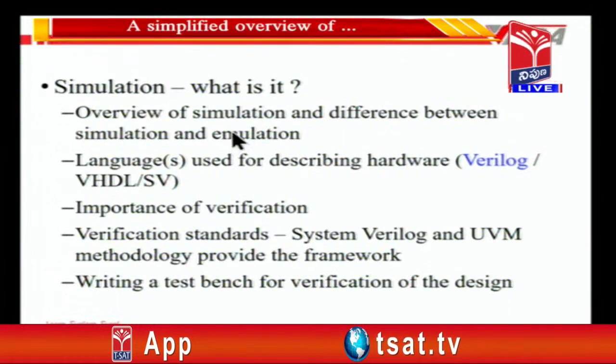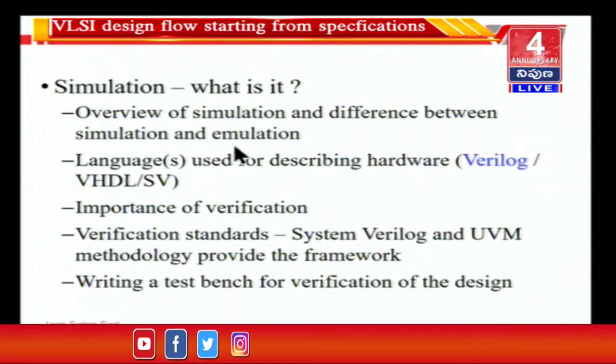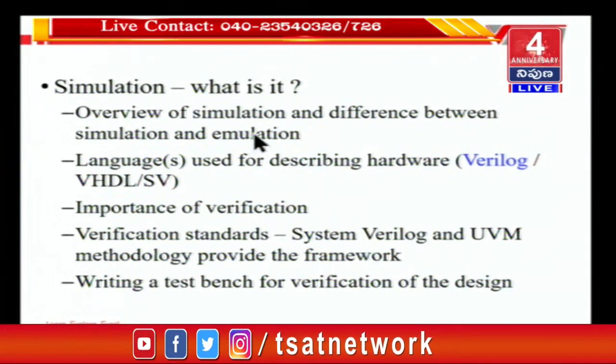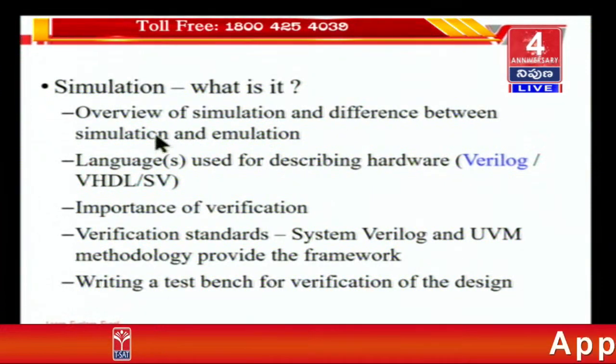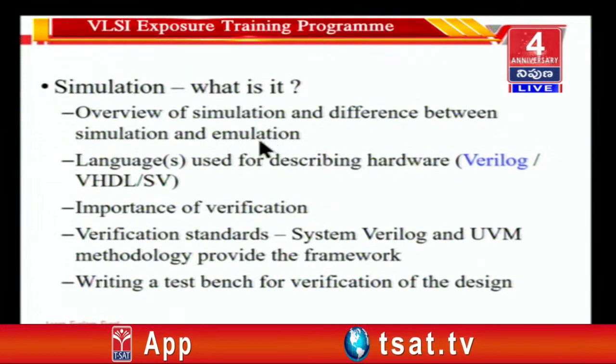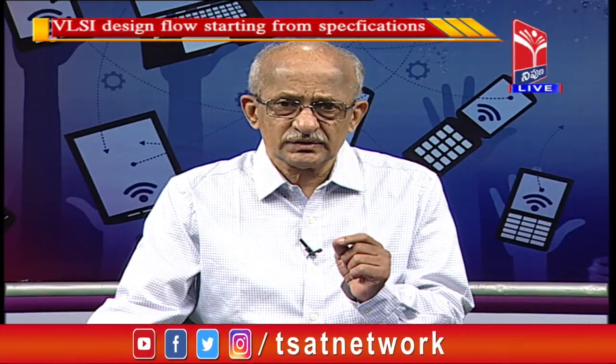Emulation is verifying the functionality of a logic circuit by making a design run on another piece of hardware. This is entirely in software and this is another piece of hardware. For example, if you have developed a new microprocessor or new microcontroller, a 4-bit microcontroller with some specialized instructions, for use in, let's say, an FMCG product.